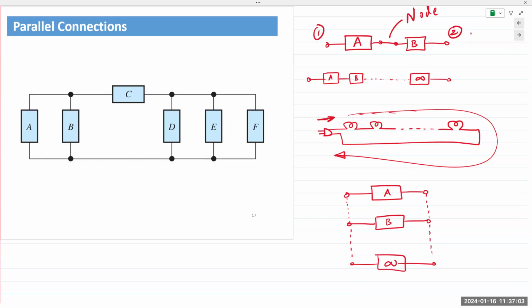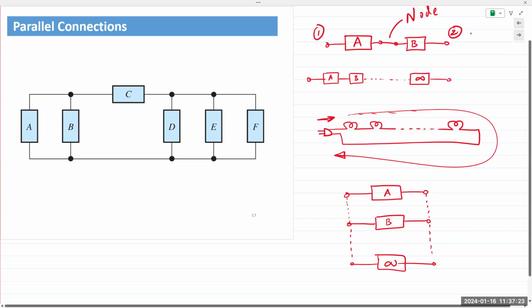Pop out those 2 screws, take out the panel. You will see that there are 3 wires coming from the wall outlet. You have a 3-prong outlet, right? 3 wires for those 3 prongs, and throughout the entire strip, you will just see 3 wires going across it. And each socket is connected to those respective wires.